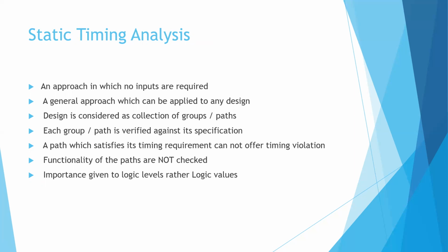Design is considered as a collection of groups or paths. It does not go into checking the functionality of the design, whereas in dynamic analysis the functionality is also checked. In static timing analysis, the functionality of the paths is not checked. A path which satisfies its timing requirement cannot offer timing violations. Importance is given to logical levels rather than logical values.